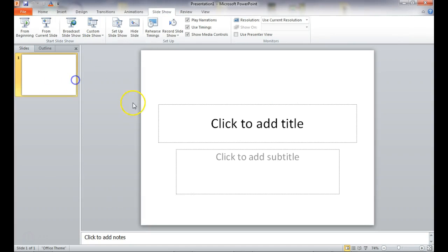Technically, bandwidth is the range of frequencies a media can reliably pass. That's what bandwidth is. And every media has a certain bandwidth. So if I take a piece of wire and I put DC on it, that's okay. When I start putting AC on that thing, things happen. It couples, it creates capacitance, it creates inductance. So sooner or later, the media itself is going to block the data that I'm trying to send at a certain high rate of speed.